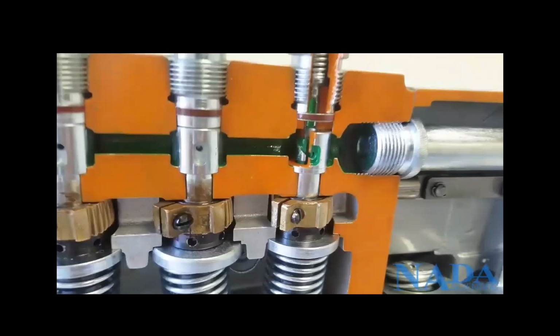So, the low pressure pump, we said that its function is to supply the pressure as a fuel to the high pressure pump. The low pressure pump fills all the cavities of this high pressure pump. All those cavities are filled with diesel fuel, and the diesel fuel continues to fill. You see this upper passage marked in green? This part is also filled with fuel.